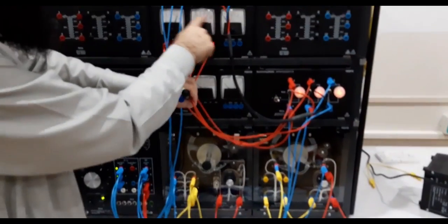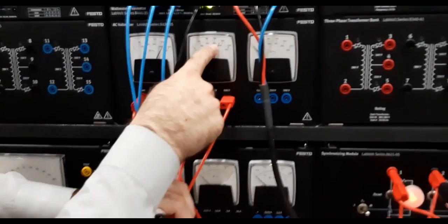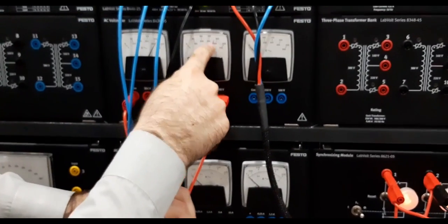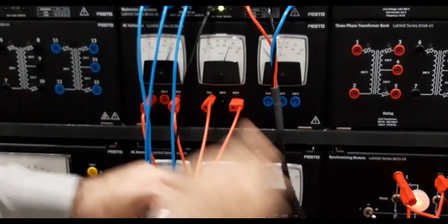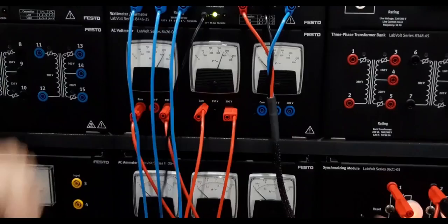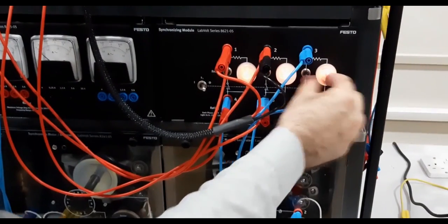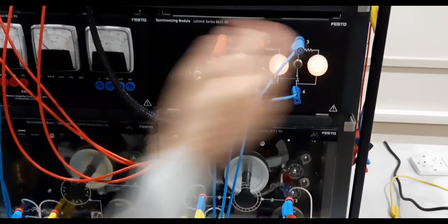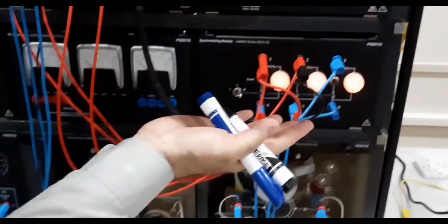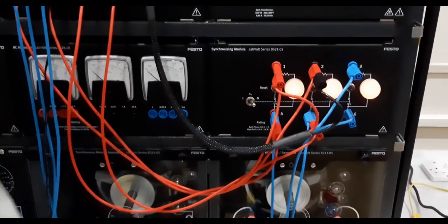Even one can see that by increasing the speed, we now achieve the induced EMF and also the terminal voltage. So we are now achieving some voltage of the machine, but because it is not close to that of the system, one can see that the lamps are on. There is light in the lamps. Once we achieve the V close to that of the system, the lamps will turn off.